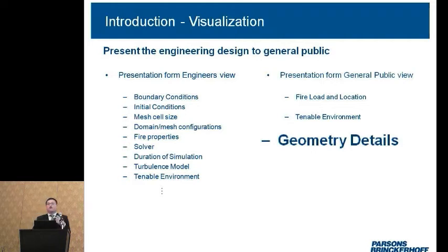So the client and authority get used to reading the 3D geometry, and they would like to see how good the 3D model is, basically. And because of the limitation of the Cartesian grid, sometimes our model in FDS has steps on it. We also have some other CFD simulations from Fluent to prove the HVAC design or other things such as pressure transients. They also read the 3D models.